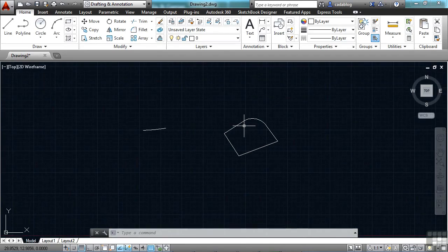It's the same thing now with a chamfer. The chamfer can do that as well. And that's a really great thing. Another thing that you can do is use the CONVERTPSTYLES command. That's a long system variable and it's a command, but it lets users convert the current drawing to either a named or color dependent plot style. That's just a different way of managing your layers and line types and layer colors and line thicknesses when they print. If you're going to use a CTB file or an STB file, this is just something that will do that change for you on the fly.